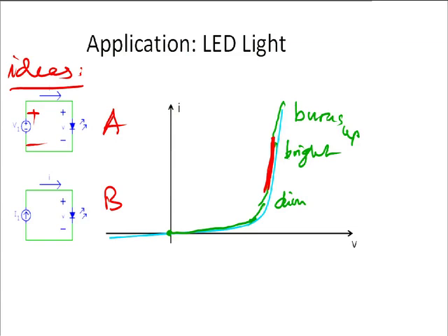The voltage, let's pick the voltage somewhere here, so that this thing actually has a chance of putting out light. Okay, so if the voltage has this value, approximately 3 volts for a typical LED, then the voltage source says I want to be here. The LED says, oh, I want to be here, and then the compromise is where they intersect. So that's going to be the current that flows, a milliamp or so.